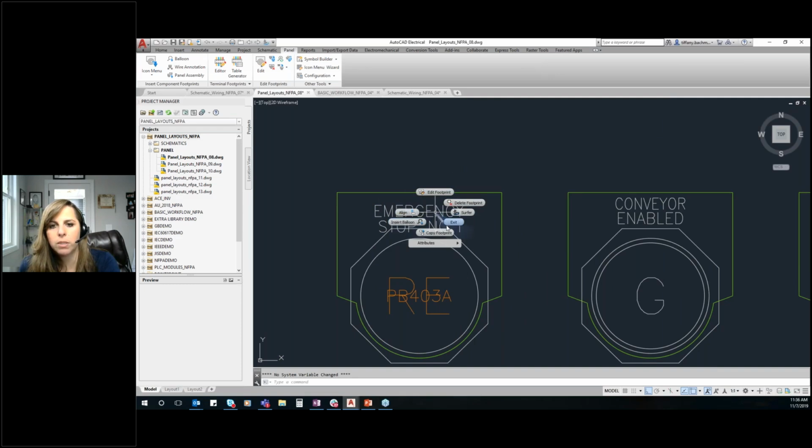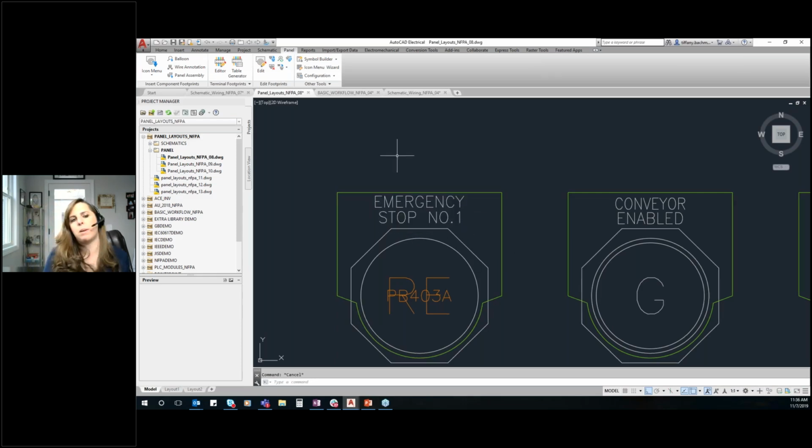And we can even do really easy editing of attributes, things like that. I can move with the grips, or I can use the attribute tools to actually move these attributes in these blocks to get them to fit, things like that. You can make small adjustments. The key to AutoCAD Electrical, though, is there really should not be manual effort. So it should be one-off times where you have to do that. If you're doing it every time you insert something, something's probably up with the block.